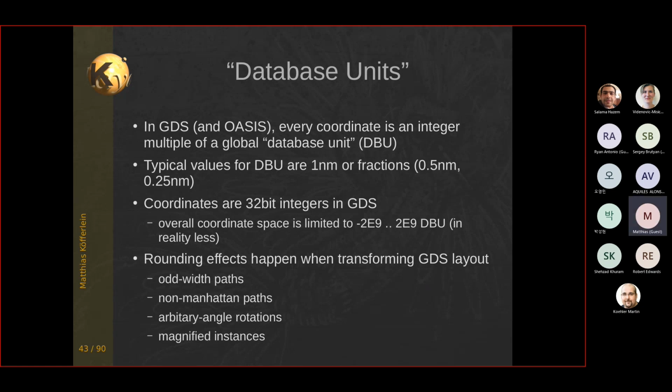And that's why basically KLayout also supports 64-bit coordinates, but you need to compile it in a special way. And some people do because they use picometers as database units. But if you imagine that a single atom is like 1/10 of a nanometer, physically it doesn't make sense to go below 1/10 of a nanometer. I don't know what they are doing actually, whether they work with subatomic particles, but technically this is something to consider. And yeah, I think you won't hit this boundary, but just in case you plan to draw your